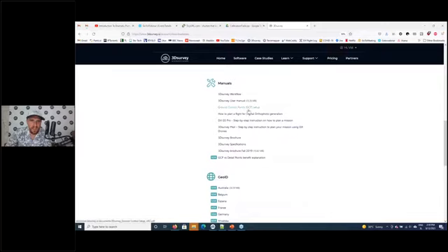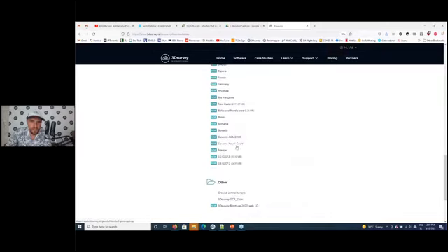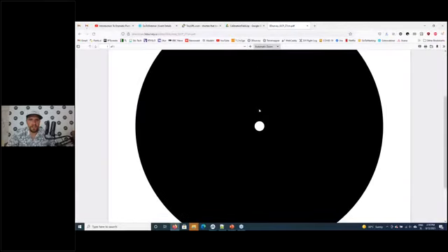There will be the ground control point target 27 centimeters. You can take this 27 centimeter target, maybe scale it 10 times so that it will be only 2.5 centimeters big. Paste it on the facade, measure it with the total station, and then use them as ground control points.